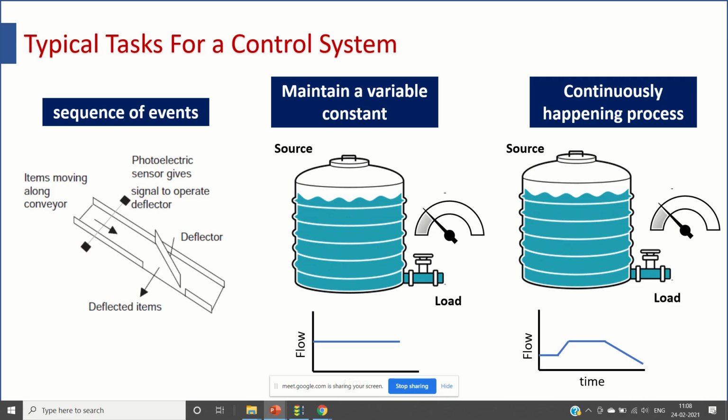mostly digital in manner. You can see here that the particular example that we had taken was the example of a conveyor that is continuously moving. So there is one motor that is continuously keeping the conveyor in a rotating mode. Then you have got one photo sensor and a source of some sort, maybe it is a laser or it can be an IR source. Whenever some material comes in between the source and the detector module, then there is an intermittence in the optical path. That means the optical path is disturbed.